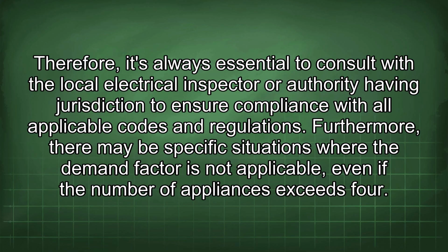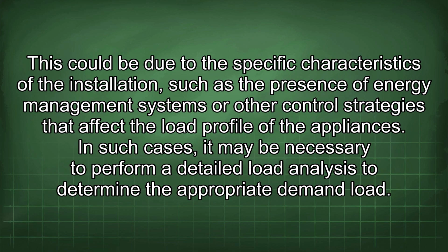applicable codes and regulations. Furthermore, there may be specific situations where the demand factor is not applicable, even if the number of appliances exceeds 4. This could be due to the specific characteristics of the installation, such as the presence of energy management systems or other control strategies that affect the load profile of the appliances. In such cases, it may be necessary to perform a detailed load analysis to determine the appropriate demand load.